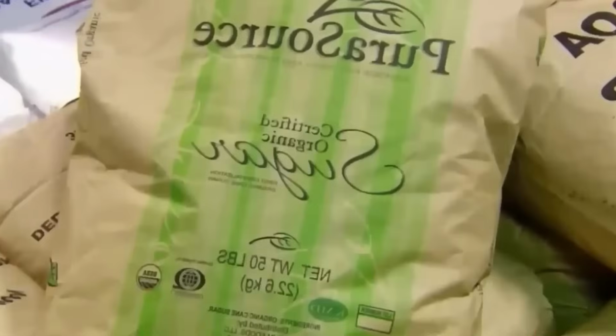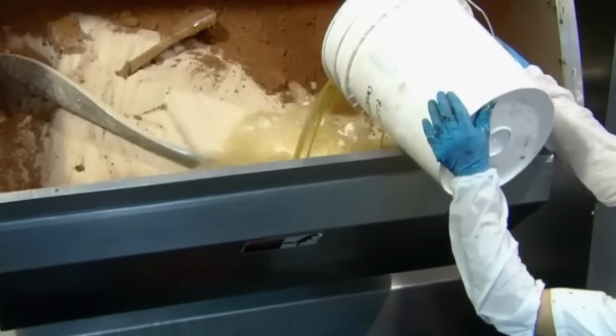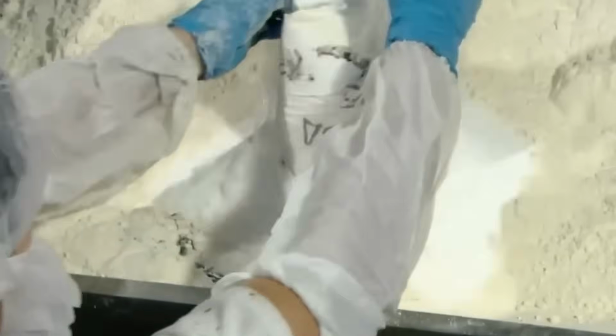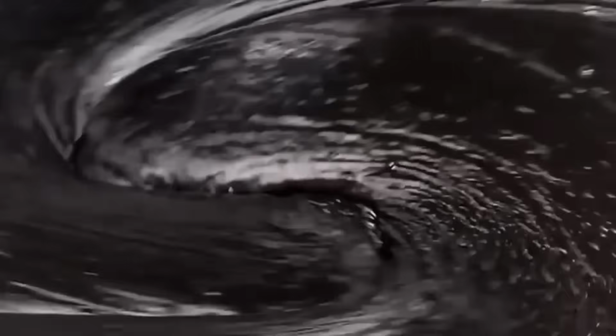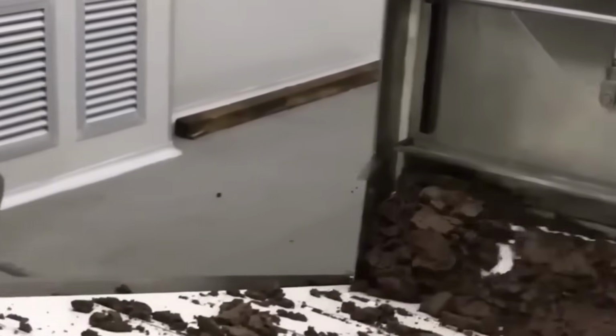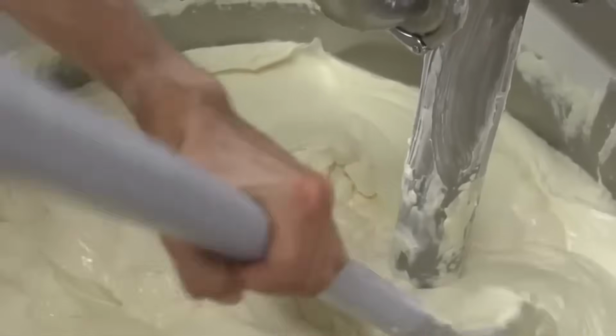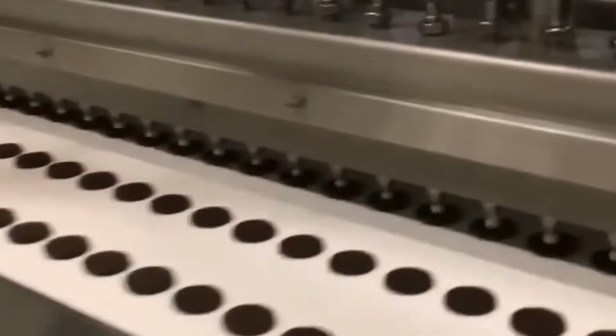The finished cream is transferred through insulated stainless steel pipes to pressurized holding tanks. Agitators maintain cream fluidity and prevent phase separation. The filling is then pumped to multiple servo-driven depositors aligned with each lane of the wafer roll conveyor. Each nozzle delivers a calibrated cream column into the core of each roll, with filling weights accurate to plus or minus 0.2 grams. The nozzle retracts dynamically during deposit to ensure central cream alignment and full core penetration.